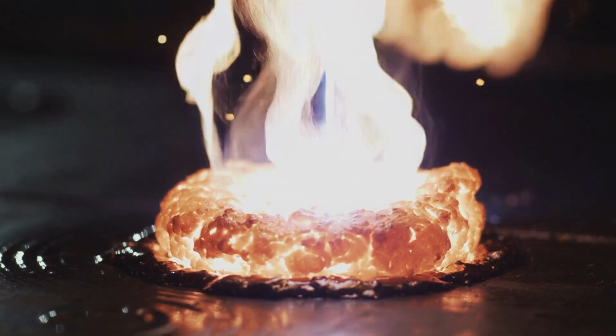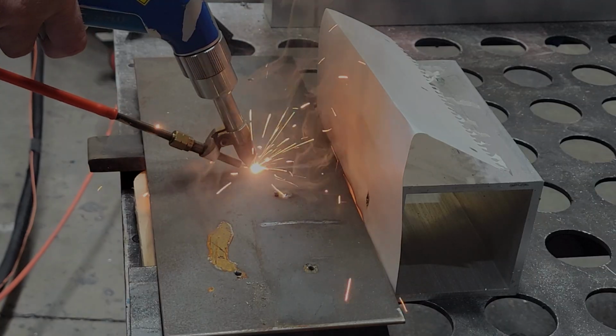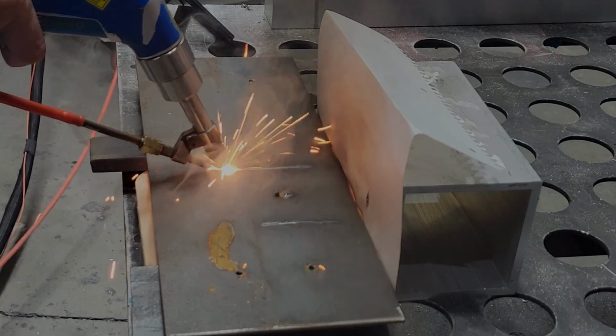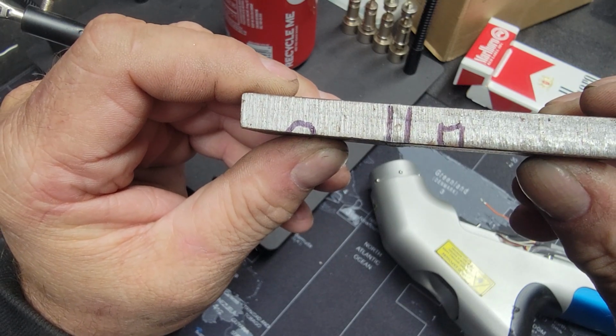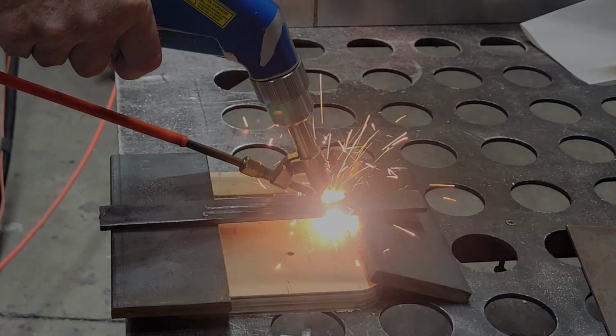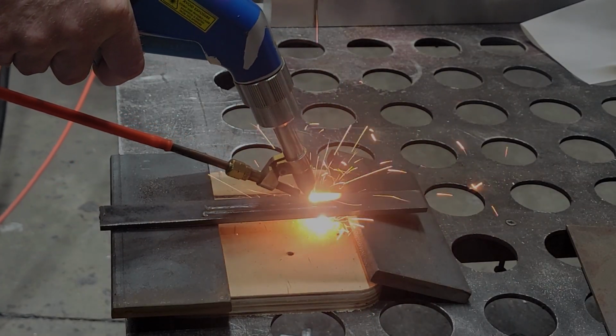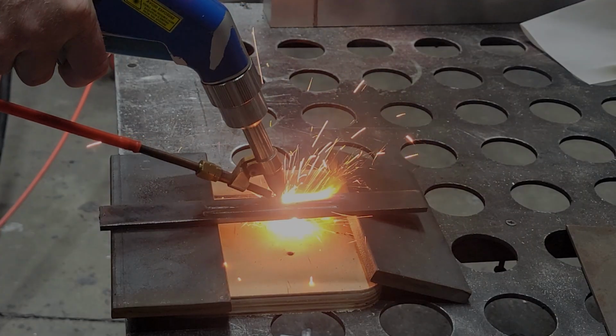Thickness effect. Thin material: photons penetrate quickly. The energy density builds fast, and plasma forms almost immediately. Thick material: a larger volume must be excited, so the beam requires more dwell time, meaning slower travel speed, to deliver sufficient energy per unit depth to reach the plasma threshold.